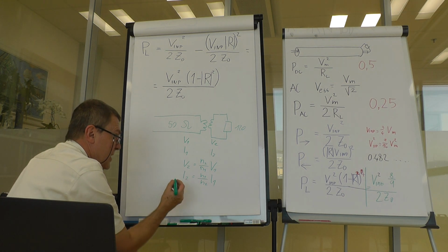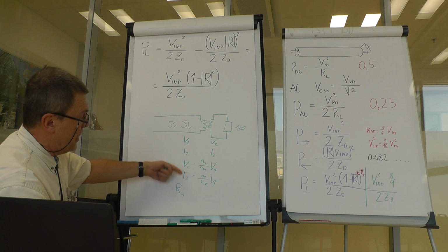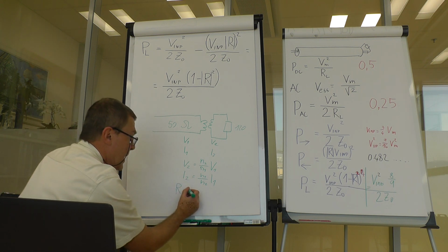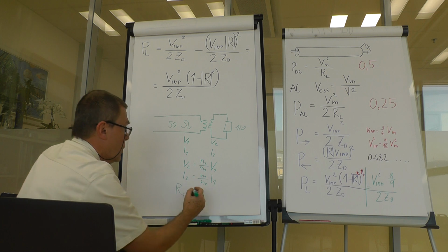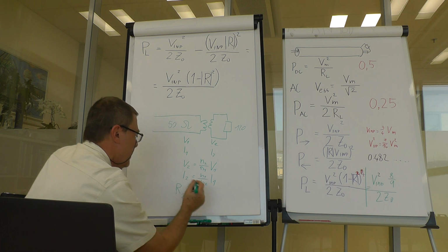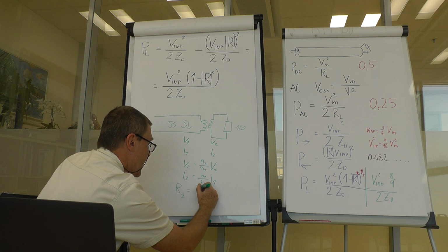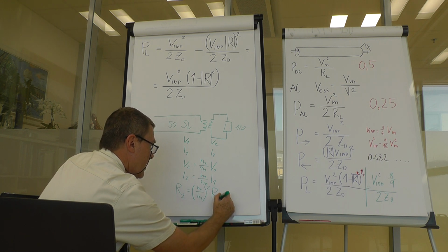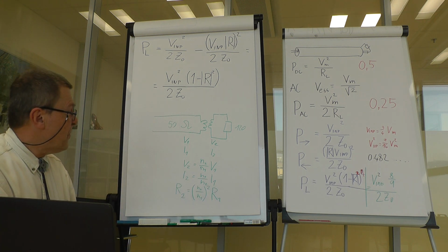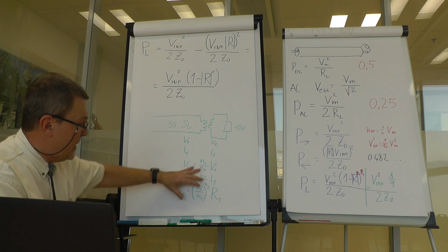impedance or resistance. So if I call R1 the voltage divided by current on the primary side, you would get R2, to have the same phase for all the equations, that would be N2 divided by N1 squared, times R1. Which means that I can transform the impedance.